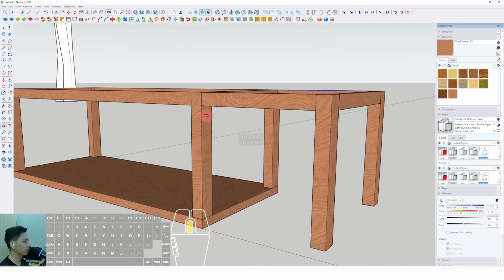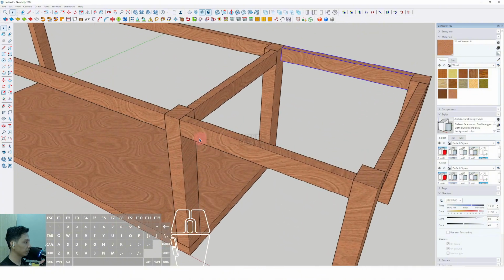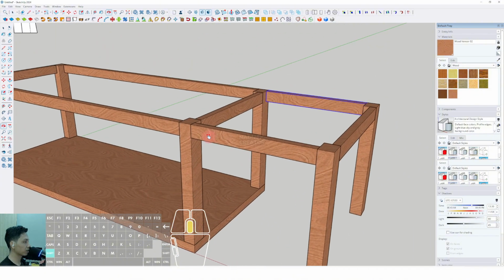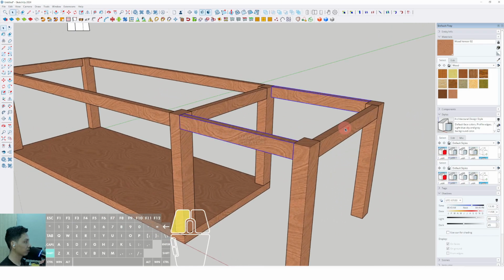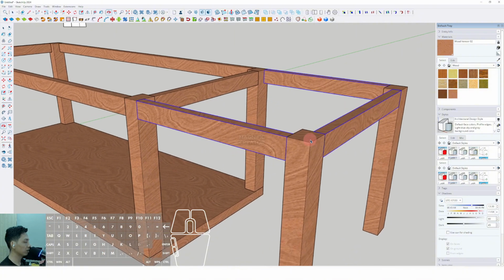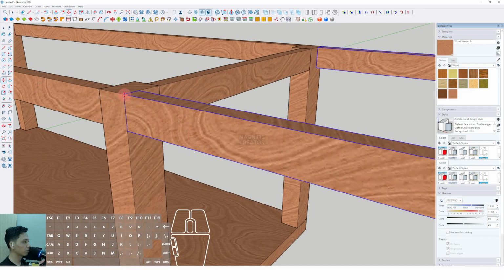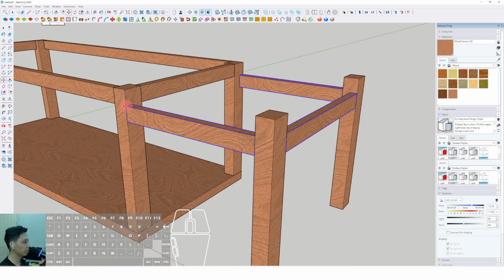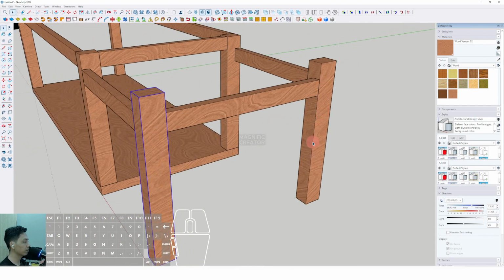Now we can also set up the elevation of this top table and this top bench. You can click all of this frame on this table, sorry, this bench. Then we can select move and click from this point and move it a little bit, around 40 millimeter, enter. Then we can click both of the frames, right click, make unique.